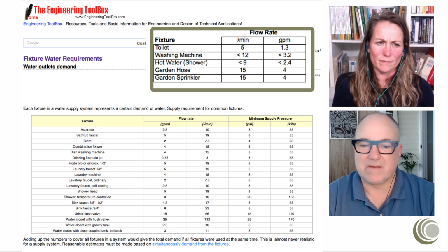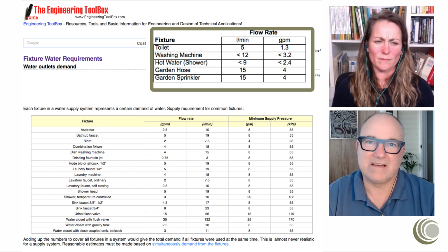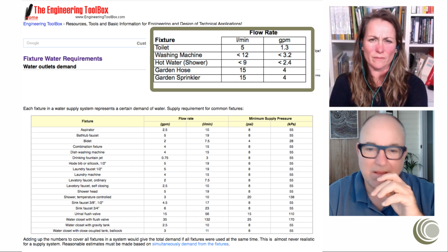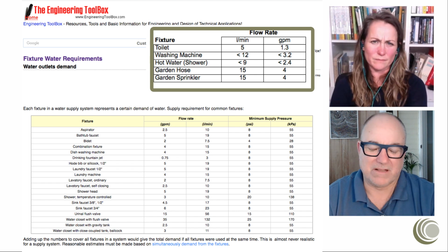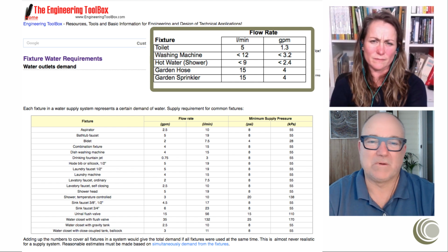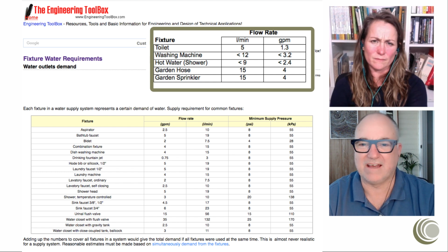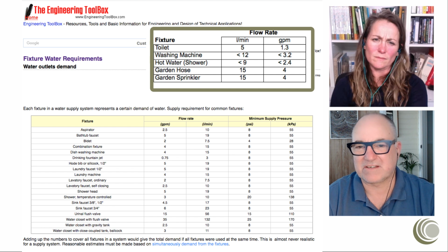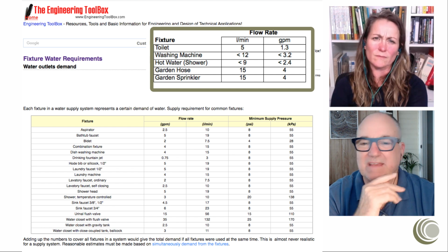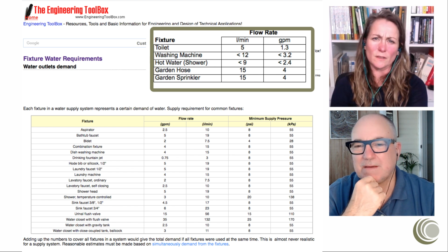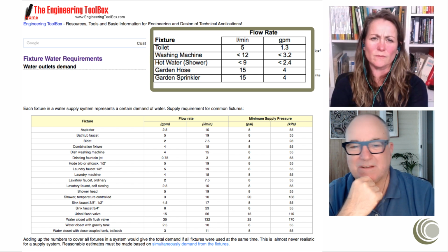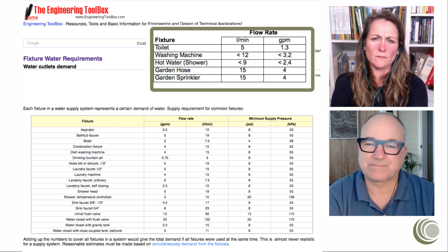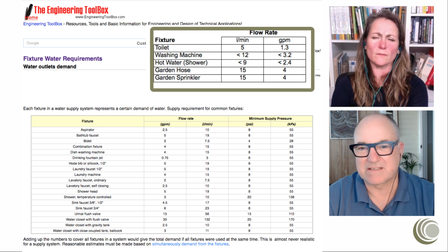So there'll be a friction loss in the pipes. The other thing we do is there was a standard in Australia, which we ignore now, that said rainwater supply lines need to be smaller than mains water supply lines in the house. What that ended up doing is maximizing friction head loss. So the rainwater supply lines were 15 millimeters and the mains water supply lines were say 25 millimeters, just for argument's sake.